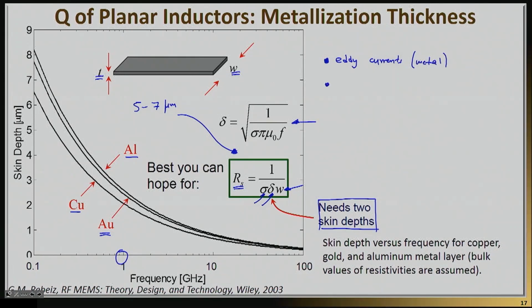And secondly, you have also other issues such as non-ideal sigma and roughness. So what I mean by non-ideal sigma is the conductivity of the metal, and most of us will just open a manual and say, what's the conductivity of copper or aluminum, write it down and plug it into that equation. The reality is that thin film metals have non-ideal sigma. Typically, they have conductivities up to 50% lower than the bulk one. So thin metals are not bulk metals.